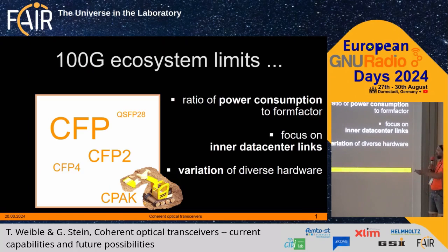Those acronyms, CFP and CFP2, are form factors used to enable the pluggable transceivers. When we look at the CFP, for example, it was a great design in that we were able to put a lot of components in that pluggable module, but it had a huge drawback. It took a lot of power, and in terms of size, it was really big.